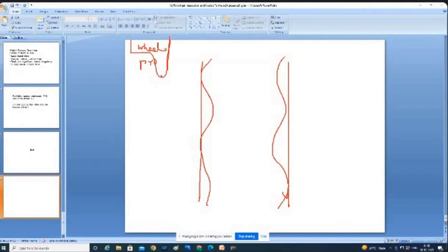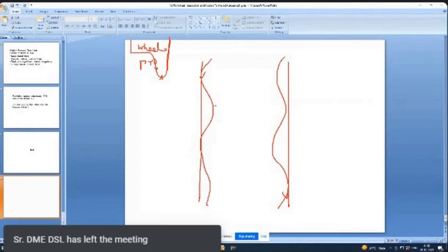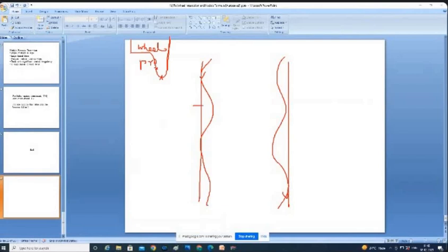If you take a point on the flange, the tip of the flange, or any one point, and draw a trajectory like this, this point touches here and then gives a gap. That means in this position you have to imagine that the rail will be like this and the wheel must be like this, so a smaller amount only will be on the rail table. So this is the meaning.